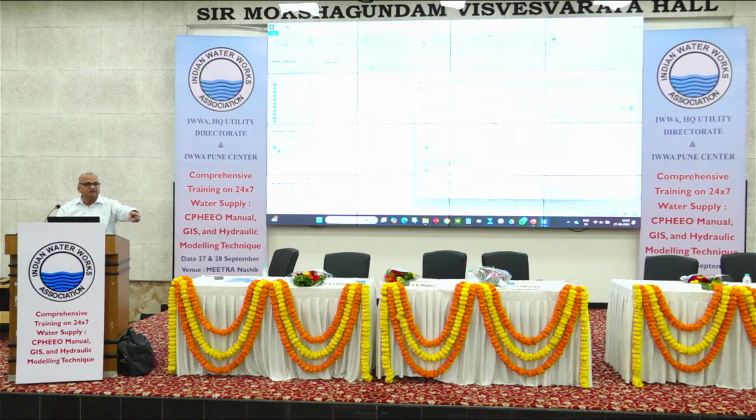In the morning session I demonstrated how the shapefile is created for the pipes. So I have clicked this pipe shapefile, and you can see everything is there, length, etc. Say next, then say meter, then say establish connectivity, yes, then say next, then next, then again next. Now here is an important step.